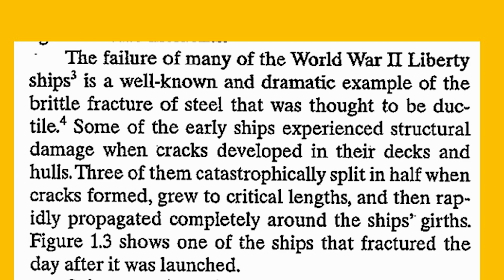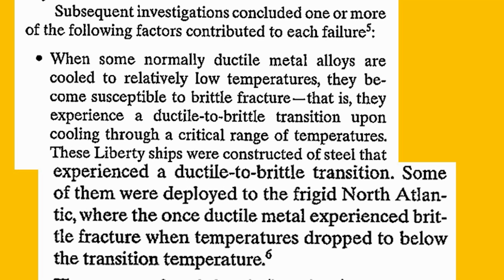And that figure showed one of the ships fractured a day after it was launched. When some normally ductile metal alloys are cooled to relatively low temperatures, they become susceptible to brittle fracture. That is, they experience a ductile to brittle transition upon cooling through a critical range of temperature.